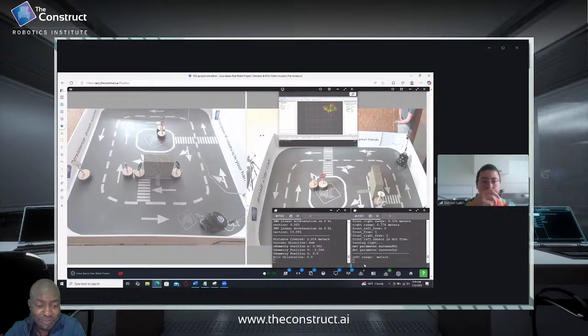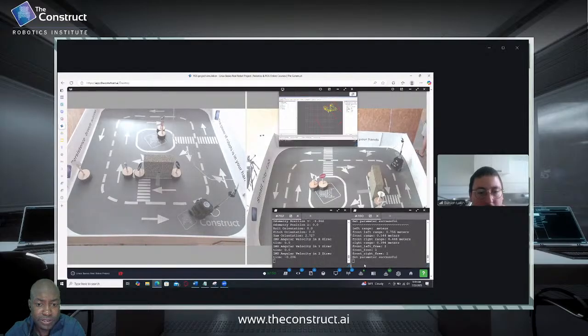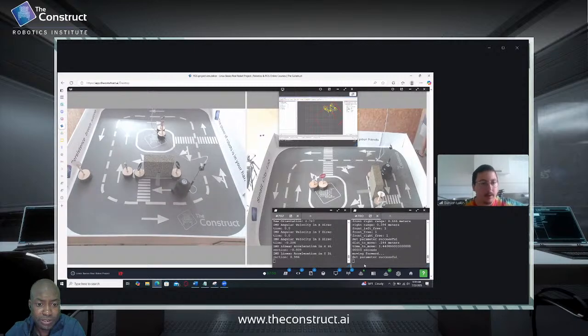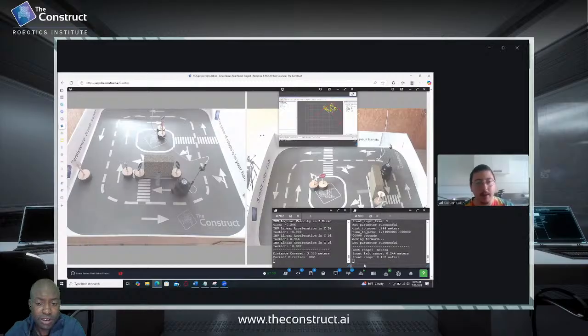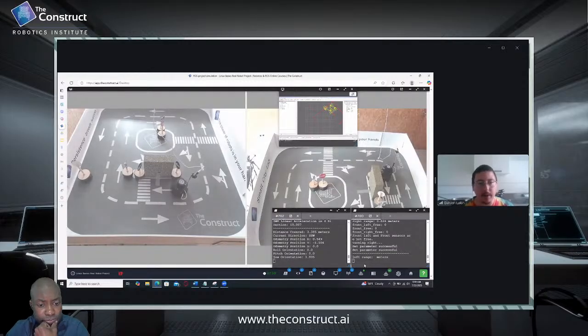So here it was free to move forward, but it encountered an obstacle on the left. It wants either all three, the right and the left and front, to be clear, or it wants the right and the left to have obstacles and then the front to be clear. But if there's only an obstacle on the left side or the right side, it'll turn until it's either all clear in front, left, and right, or only clear in front and obstacles on both left and right. Okay.